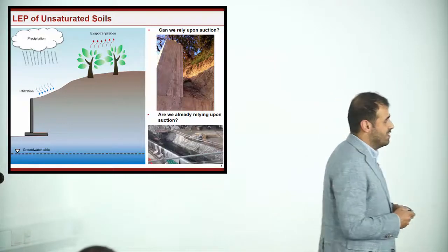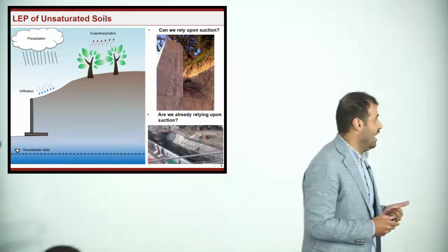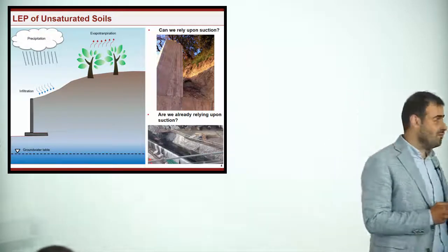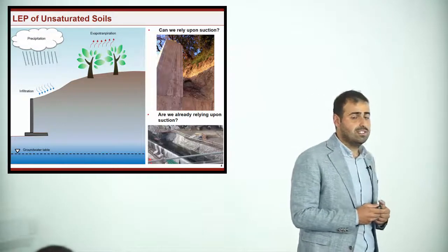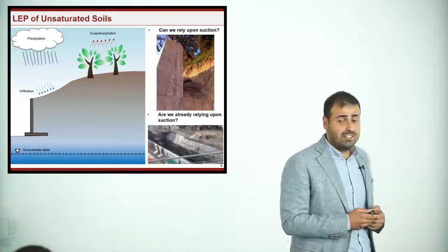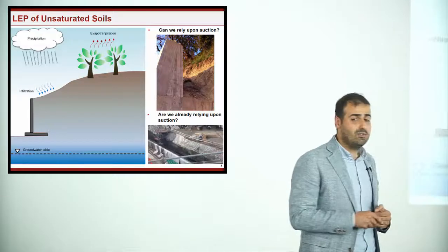So the main question that I started to ask myself is, first of all, can we rely upon suction? I've heard before that we cannot rely on it, but I would say that it depends. First of all, on what kind of soil we are taking into account, and also we have to consider the intensity and the typology of the rainfall events. Another question is, are we already relying upon suction? To this question I would answer yes.